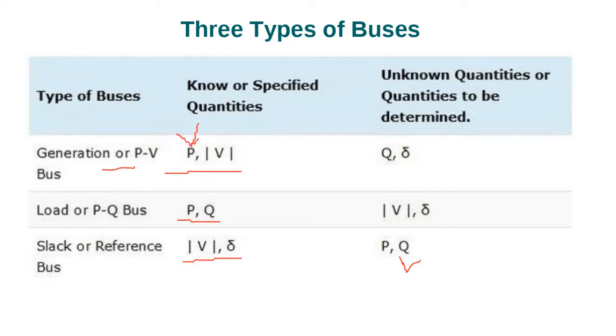For example, we want it to be maybe 20 megawatt or 100 megawatt. So we specify Al-Wajba maybe 50 megawatt, Ras Al-Afan will be maybe 400 megawatt, and so on. So we need to specify. One substation is okay. That's the load, and then we run the load flow, of course. The slack bus will be the difference now.